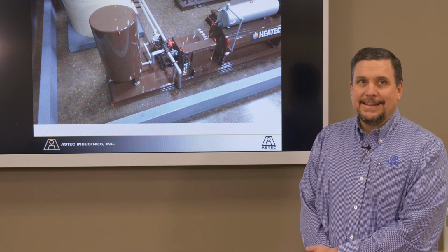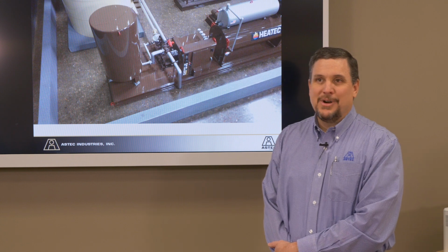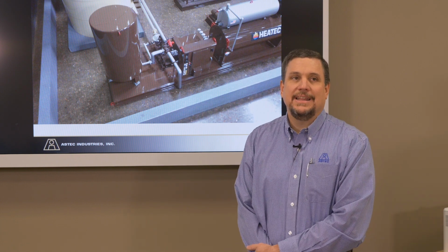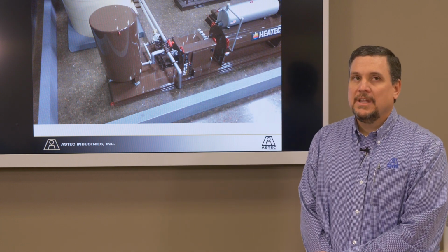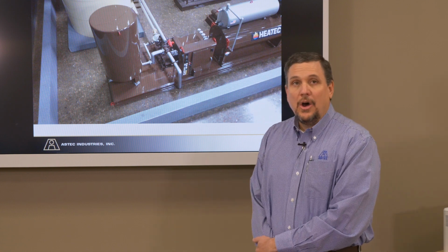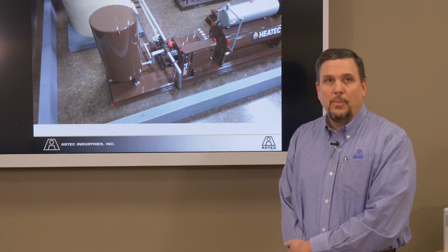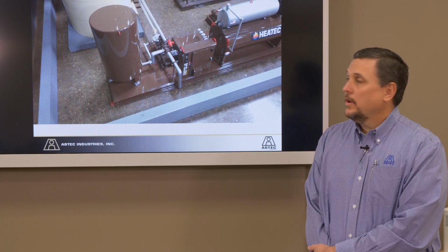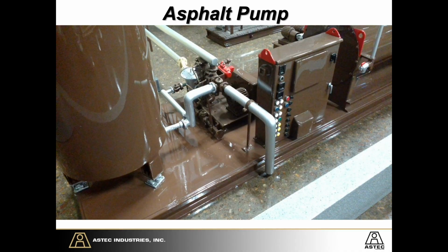One of the calls that we take a lot on troubleshooting AC calibrations is that they're not utilizing the calibration tank properly. And they're using it at a very low tonnage or very low pounds, like 500 pounds instead of 3,000 or 4,000 pounds. You have different configurations for pumps.